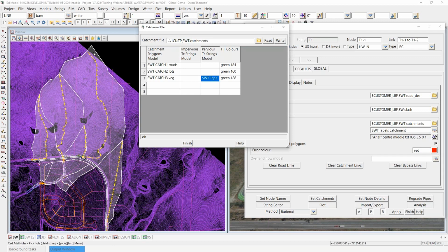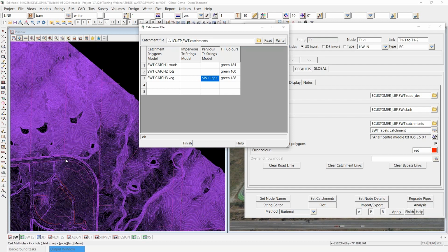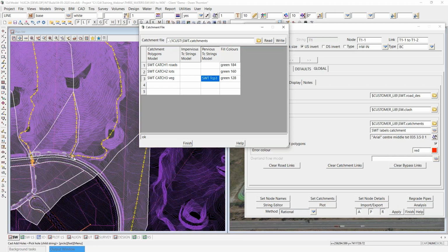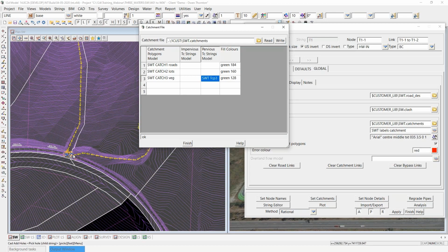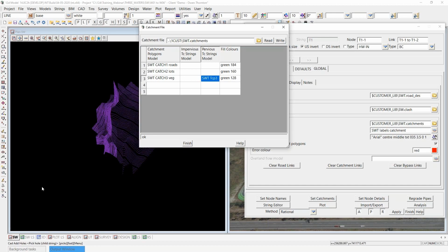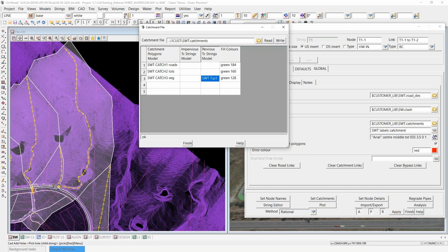For TC strings, however, a TC string doesn't have to have any levels, but you draw it from the top of the catchment, drawing to the bottom to its discharge point, trying to estimate the longest time path for the catchment to concentrate or flow and contribute fully to the discharge point. There is a requirement for these TC strings though. The last vertex, the end vertex on the TC strings must be closer to the node you want to link it to than any other inlet node, okay? So that is an important thing to note. And you can't manually reassign these ones, okay?